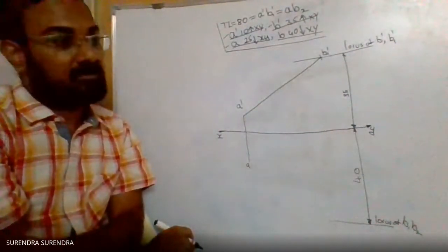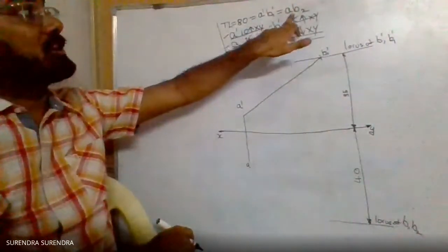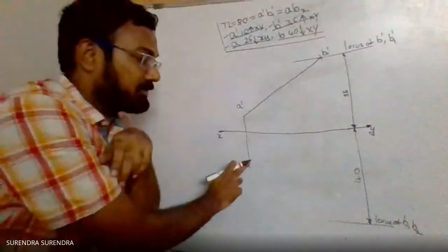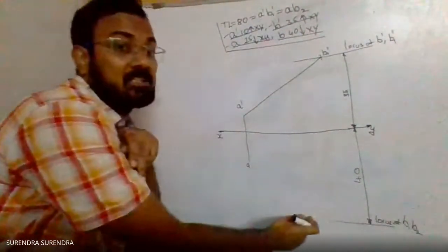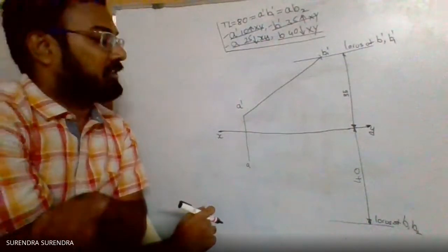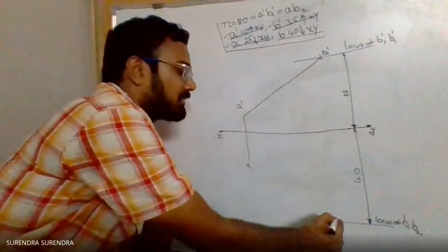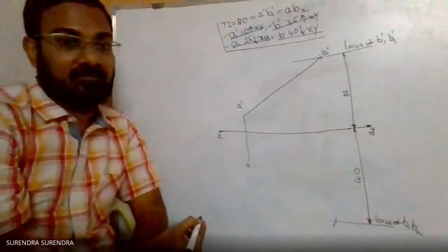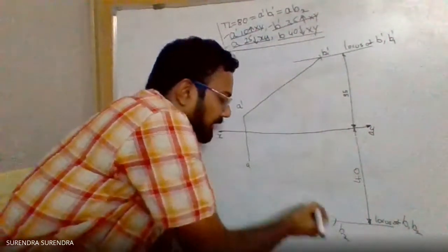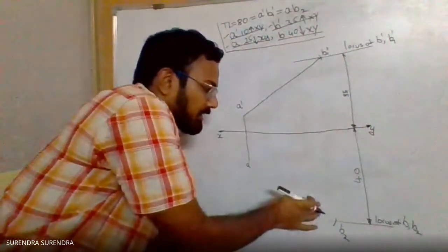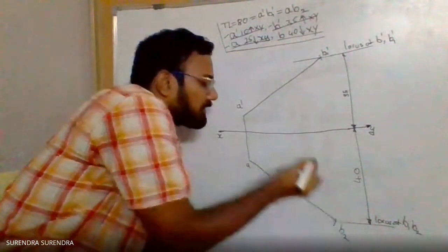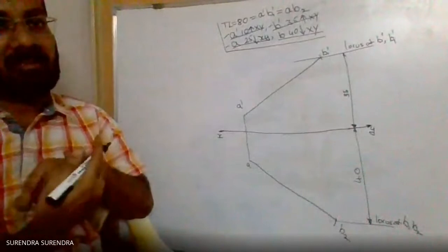Now AB2 is also equal to 80 mm. True length is also equal to AB2. So A only, B2 will lie on this locus line. So with 80 mm radius, draw an arc on the AB2 line and mark this point as B2. Join AB2 with a straight line.